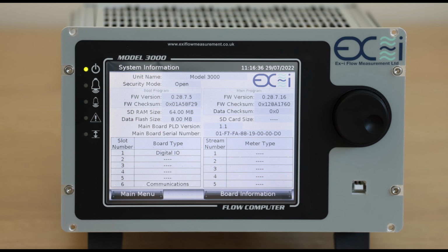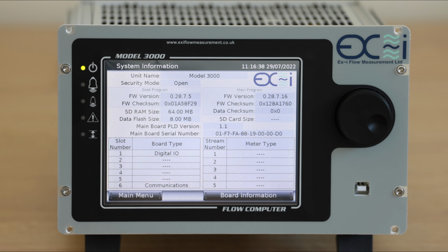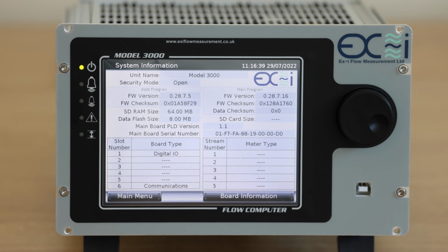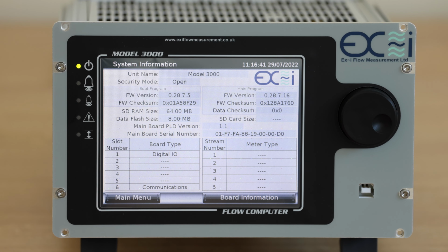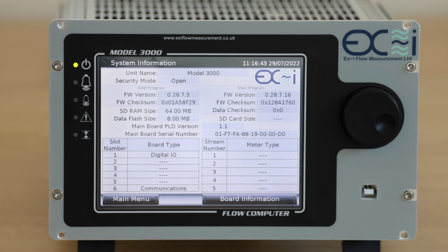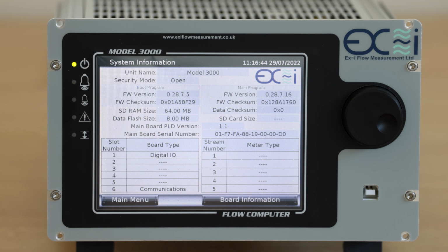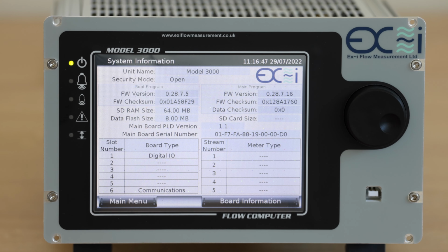If enabled in the configuration, calibration can also be performed via the edit mode on the front panel. To calibrate an I/O board, the SFC3000 needs to know via the configuration that a particular board is installed. See video 5 for instructions on creating a configuration. Run the SFC3000 configuration software and log in using credentials created in video 4.